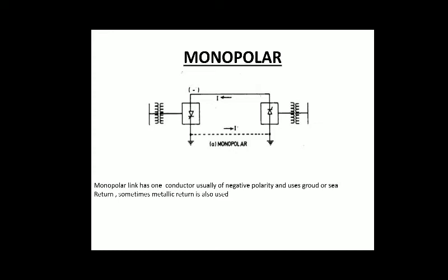As it is DC, on the right side the voltage potential is more, and on the left side the voltage potential is low. That is why the current is flowing from right side to left side, but it needs a closed path. So in this case we can use earth as a closing medium, like the missing part.